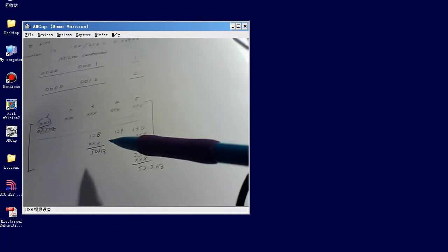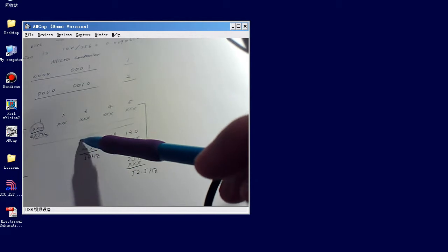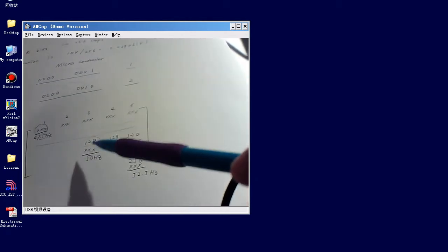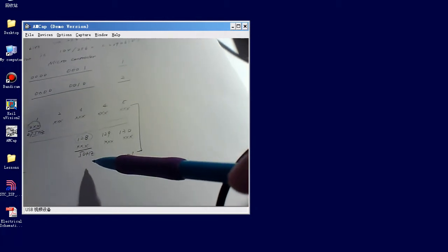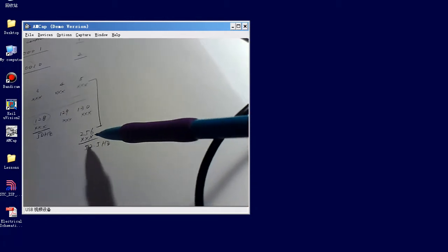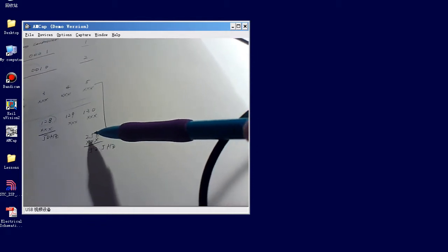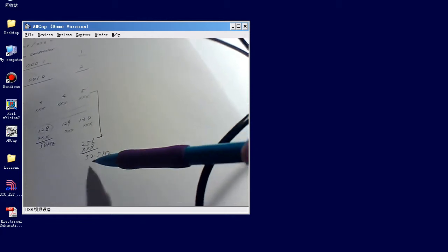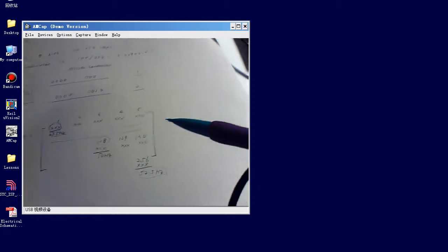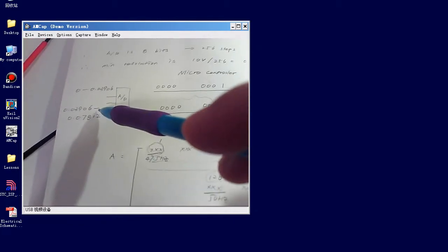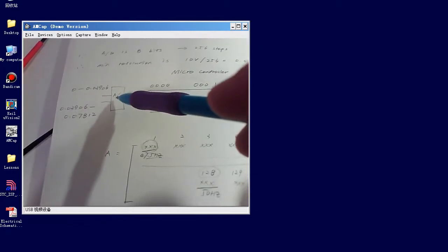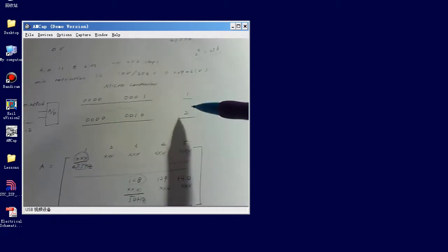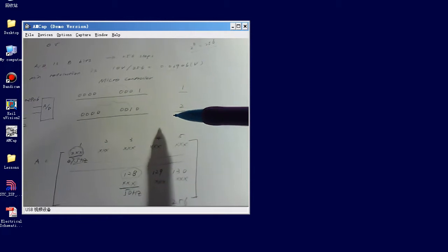If we keep going, the command located at 128 will give us 50 Hz output, and the command located at 256 will give us 52.5 Hz output. So eventually, we know the analog input we applied on the AD converter, we know that's the input in the microcontroller,